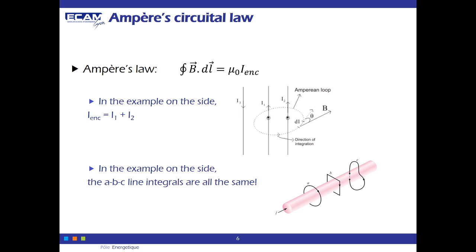For instance, for wire, instead of using such a rectangular loop, it's better to have such a circular shape where you can obtain the parameters by using the cylindrical coordinates. Because I gave you an example when we were talking about the Ampere circuit law in the past few weeks. In fact, if you try to calculate the dl for this Amperian loop, the A loop, it would be quite easy. It will be 2 pi s, the circumference of the selected loop.